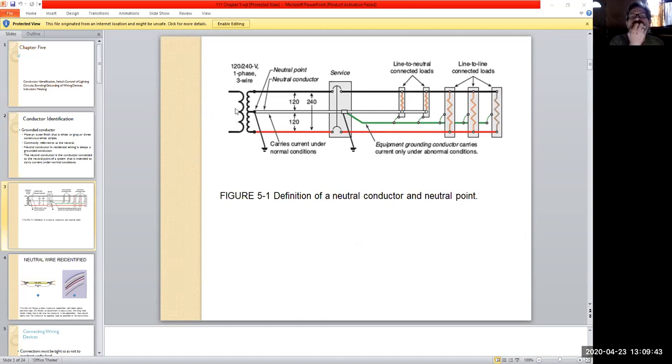If we look from the left, when you see those little squiggly lines like that, that's identifying the coil. Of course the outermost one is from the transformer, and then you have the wire taps inside, right? So the Ameren lineman or whoever comes out and taps it, and they'll pull those lines from the transformer, and that's what that identifies. Then you have the three coming in, right? We've got our black, red, and white, and it goes to your service disconnect. So we have black, red, and white going into the panel.